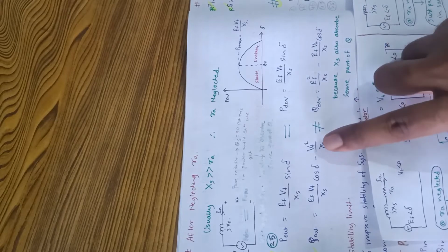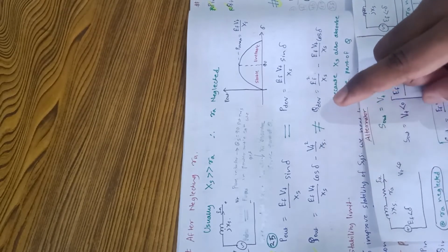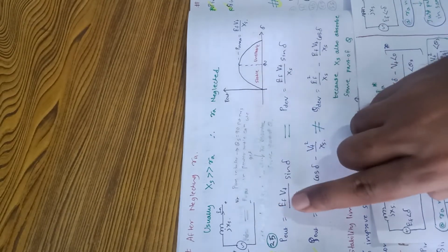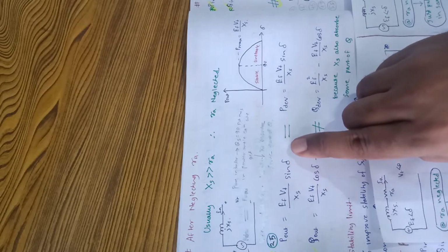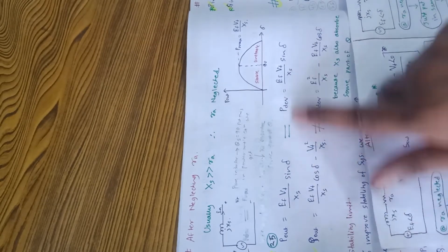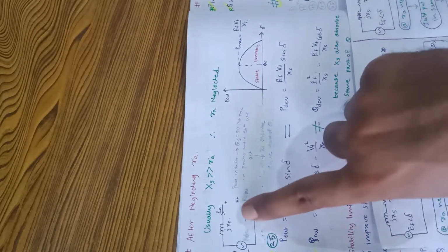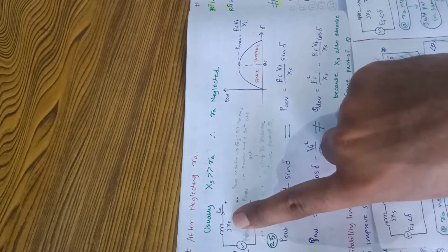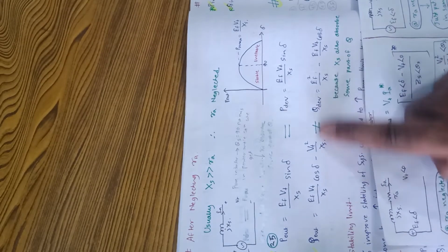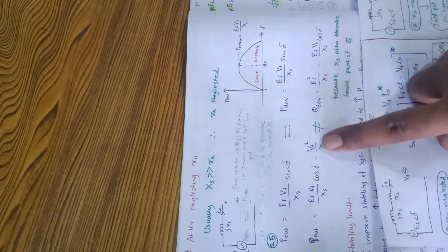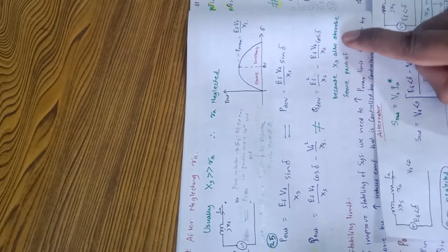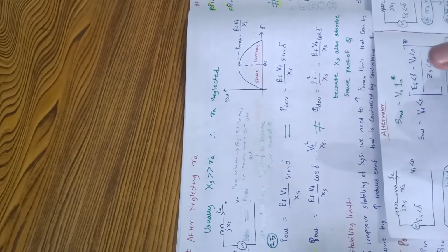One thing you can observe out here is that as we have already neglected RA, there is no consumption of active power. Active power P out equals P developed, which means there is no consumption of active power. But we have considered the reactance, so there is consumption of excess, and that's why it's not equal. Q developed will not equal Q out. Developed will always be more than the out, because the reactance also absorbs some part of Q.